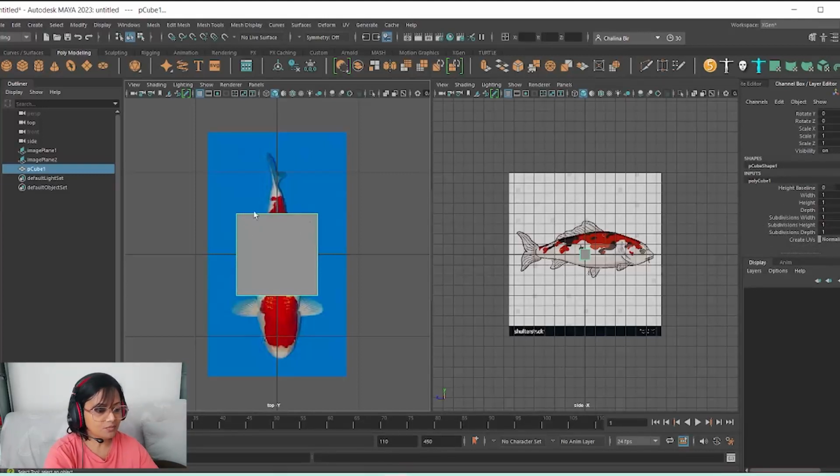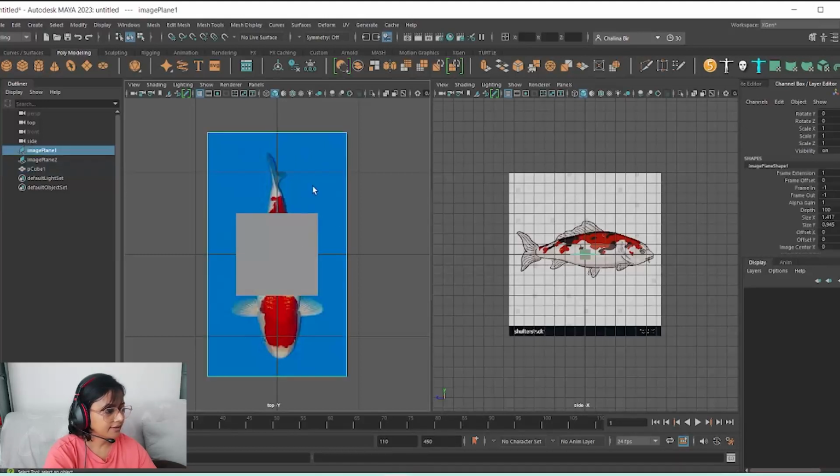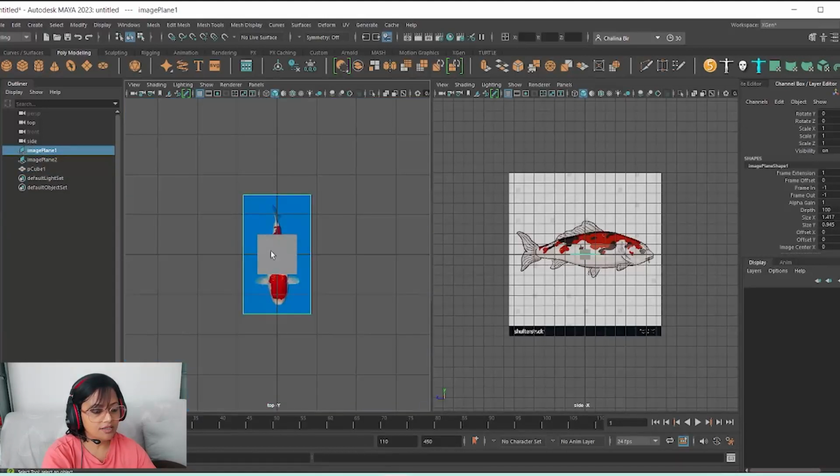As you can see in this polygon, I cannot see more vertices and edges. So I need to add more subdivisions. For example, if you change it to 20, see, now I can see all the subdivisions. Okay, so that's mandatory because without subdivision you cannot create your shape. You cannot modify your shape. Okay, so I did it. And let's go back to our screen now.